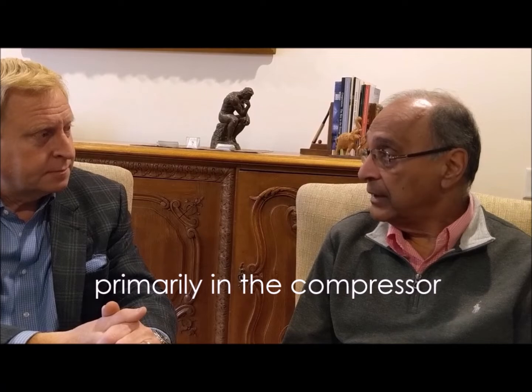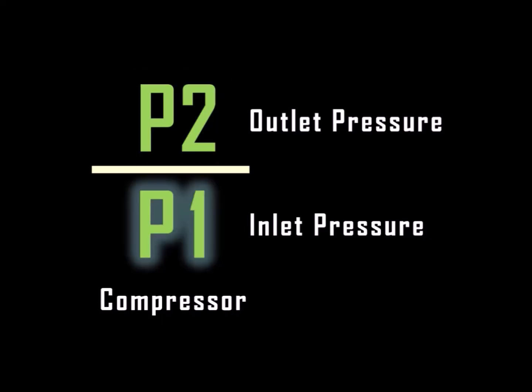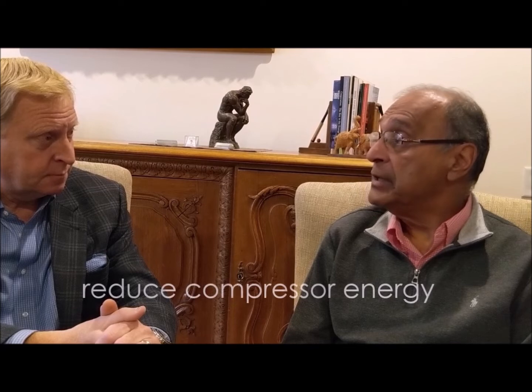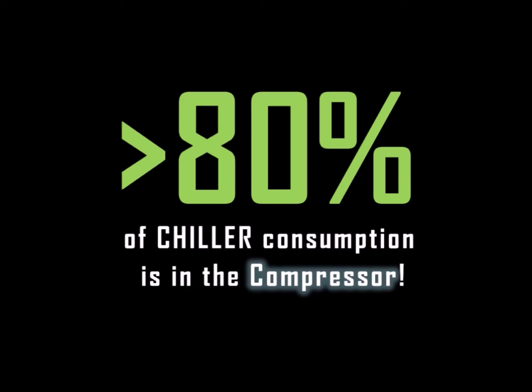The chiller's energy consumption is primarily in the compressor, and that depends on the ratio of the outlet pressure to the inlet pressure, P2 over P1. So if we reduce P2, then we can substantially reduce the energy consumption in the compressor, which is about 80 to 85% of the chiller's energy consumption. And that's what our algorithm does.